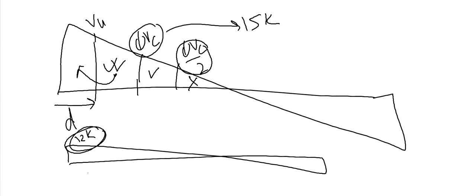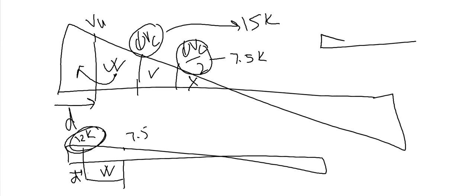So we will locate ΦVc/2, that means 7.5. 7.5 is roughly here. So calculate d. In this region we will provide the reinforcement. Now in another case, maybe in your shear force diagram the maximum value is, say, 6 kip, and this value is 15, this 7.5, that means actually you do not need any reinforcement.